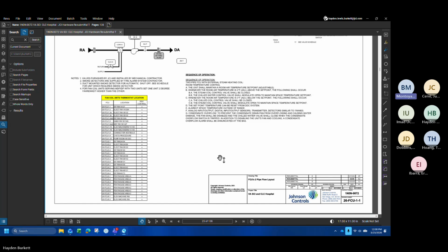And Hayden, quick question while you're jotting that down. Sure. What is the required chilled water temperature for the system to operate? Is there a range or a specific number? That's a tough question. Just to give you awareness too, for the facility, I believe we provide 46 degree, but in the course of the project, I've heard that our system in the new building maybe requires 46 for the facility and then possibly 43 for the new building.